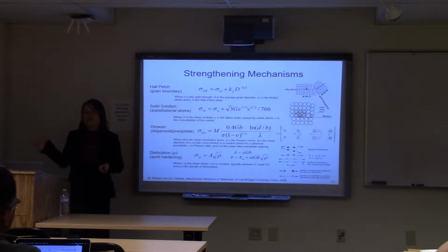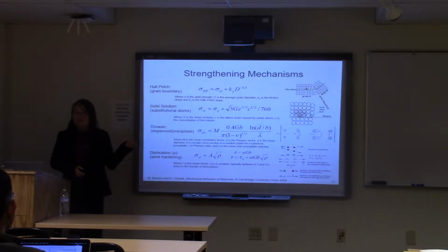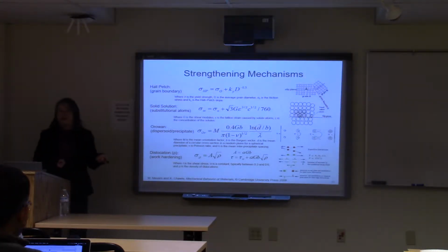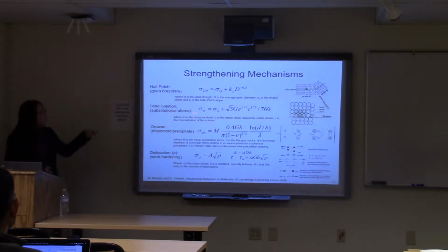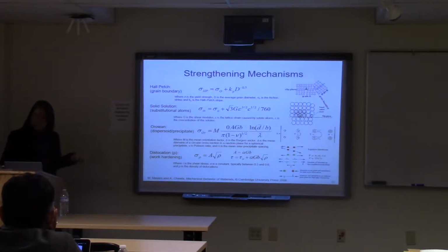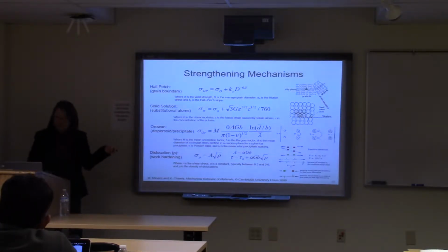Now let's look at the quantitative values in the strengthening mechanism. I kind of covered the overall strengthening from here. But in this complex system, you still have some magnesium, zinc, and copper in solid solution in the matrix. So you also have solid solution strengthening and also the work hardening from the dislocations due to the deformation. So in terms of giving a sense of the value each mechanism contributes to the strength, we need quantitative values for the grain size, the interprecipitate spacing, and the size of precipitates and the volume fraction here.